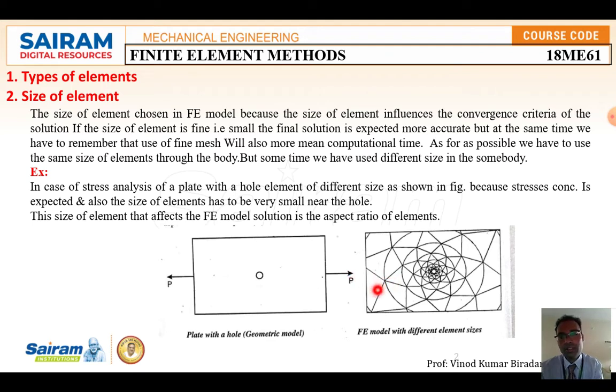The main concept behind this is that if you divide into more number of elements, you are going to get a more accurate result. You have to remember this in this slide, that is size of an element. Here we are going to calculate the stresses and strain, where the maximum stress is and where the minimum stress is, with the help of software.